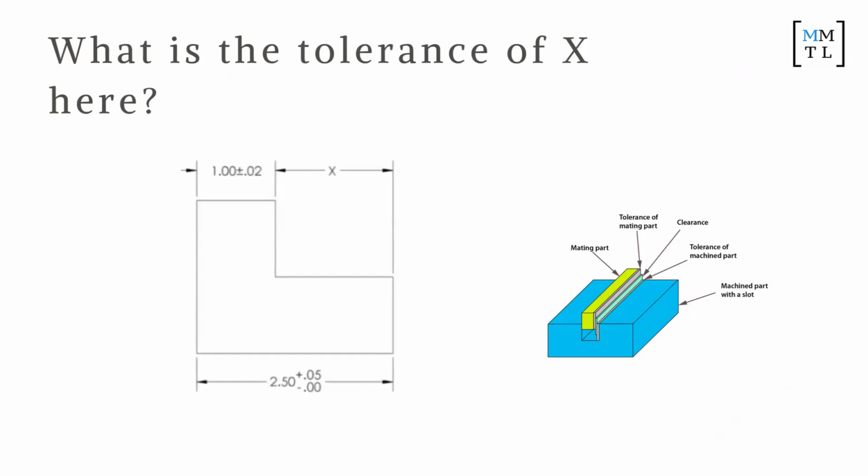So here's just a little exercise on X. Let's discuss with each other what is the tolerance on X, the plus and minus. Plus 0.7 and minus 0.0. That's the worst case, so you need to stack up the pluses. So plus 7 and the minus. There's no tolerance on the bottom one, so it's just minus 2.